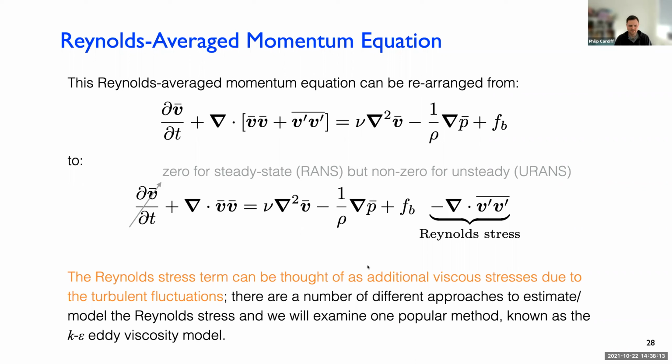So how do we approximate this? One way to do it is using these so-called eddy viscosity models. This is maybe the most common RANS approach, and there's a variety of different turbulence models within the eddy viscosity realm. The idea is, at a high level, when the average velocities and average pressures are flowing through very turbulent regions with a lot of mixing, it feels like the viscosity is increasing in those regions.